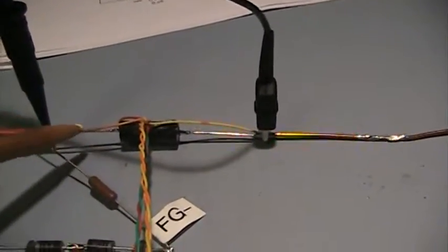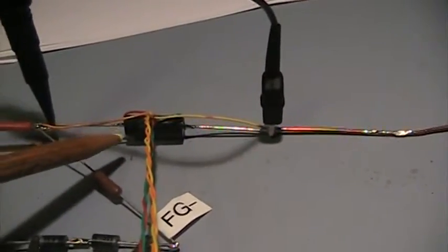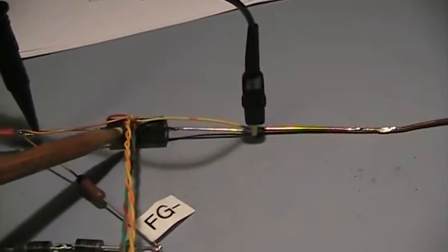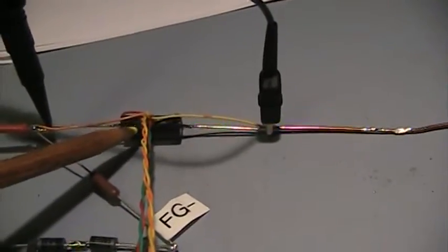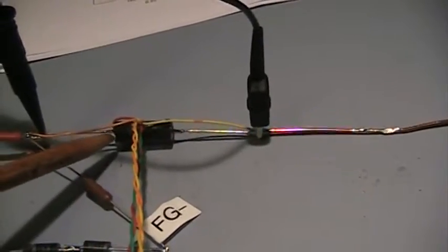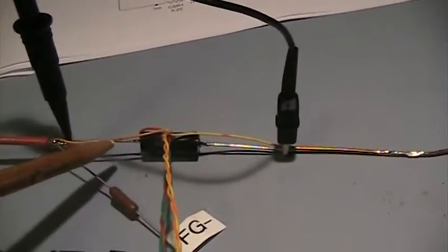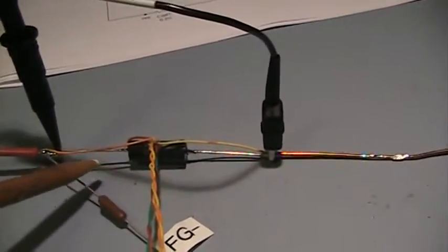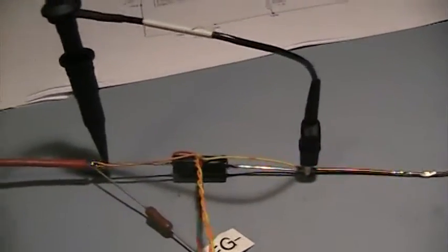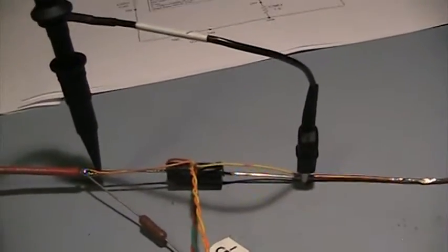So essentially what we have is an inductor in series with the CSR resistor, and we're not getting a true picture of the current through the circuit, the real current, or real power, if you will, in the circuit when we're not measuring strictly just the resistive part of the CSR. So when we've got parasitic inductance involved in between the probes, we know that our readings are going to be incorrect.